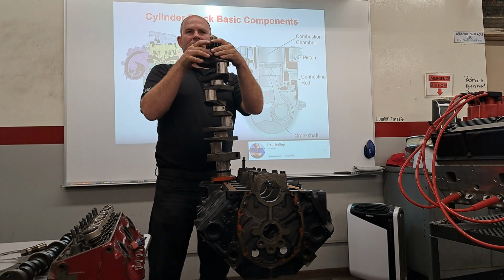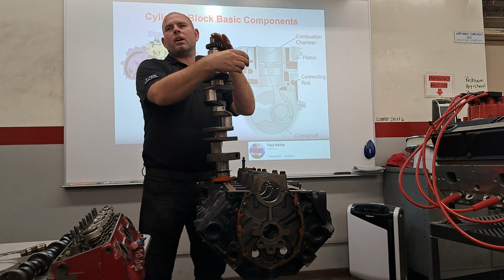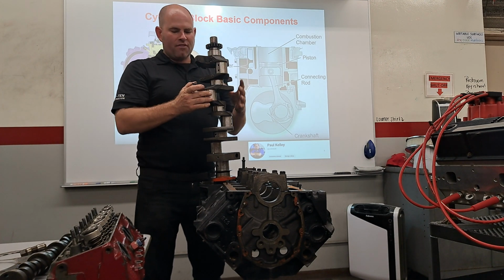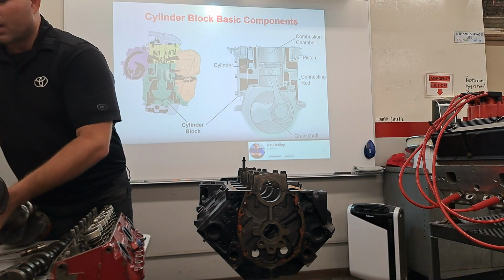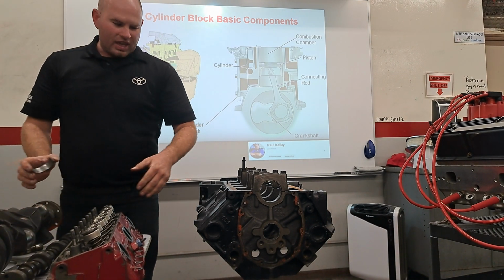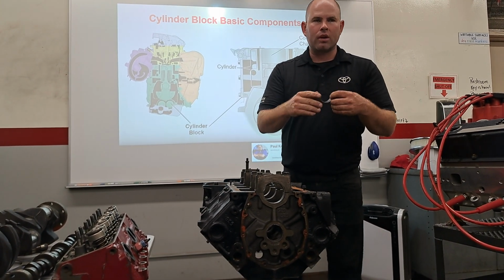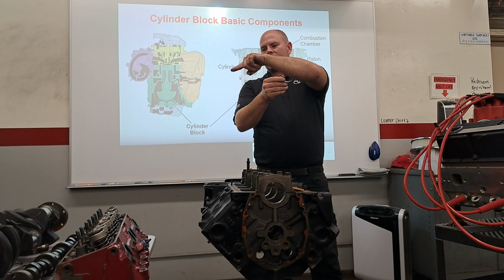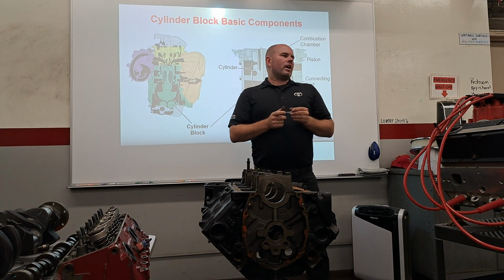Spins. It'll follow it, it'll spin. That's a spun bearing. Think about if I were to have that happen. Not only, yes, it would spin on the saddle, right? And that would probably mean having to line bore it, but also, didn't it just wreck the journal on the crankshaft? Yeah. So I can get a new crankshaft, and that's probably preferred, but crankshafts are expensive.